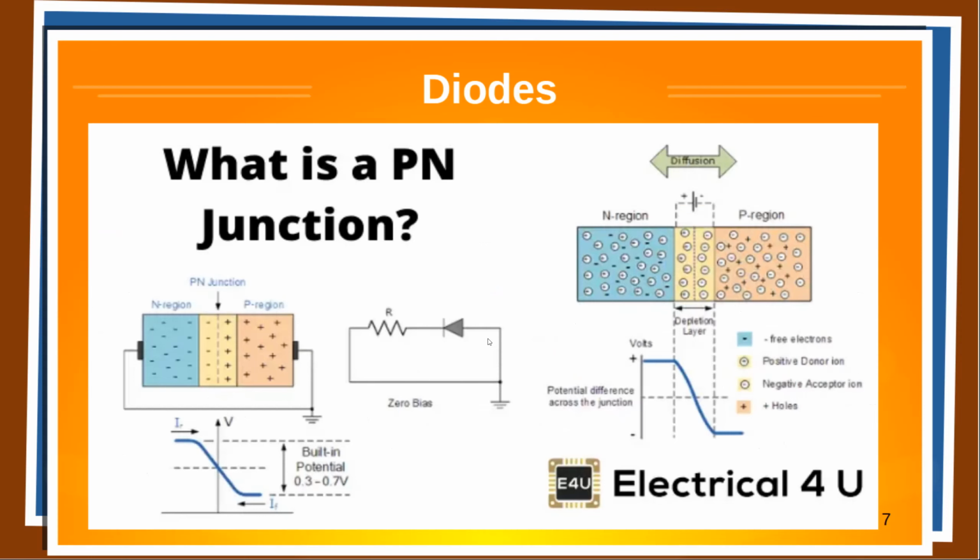So the P-N junction, we saw this same chart before, so no difference. The depletion region, the two materials conducts in one direction, has a built-in potential difference of 0.3 to 0.7 volts. Some of these other diodes, I think, can get below 0.3, depending on the material.